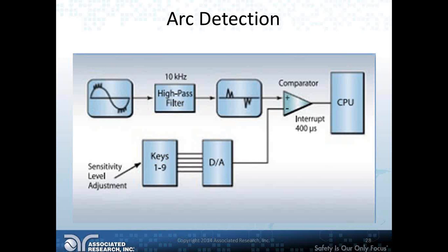So why is arc detection important? Well, an arc causes momentary high-frequency current spikes that ride on the low-frequency current waveform. Although these current spikes may not be the result of a catastrophic breakdown of the device's insulation, they could indicate a problem with the insulation system that might become a safety issue at a later date.